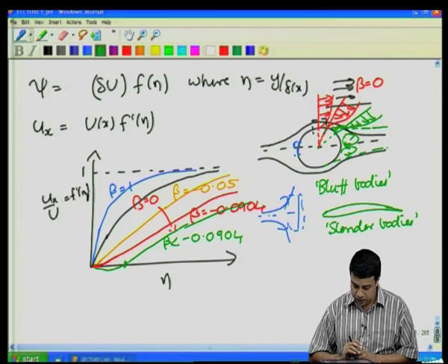So, this tells us that even though potential flow may predict solutions, they are not always valid, because the potential flow solution will be valid in most of the flow only if the regions where the viscosity becomes important are restricted to thin regions near surfaces.